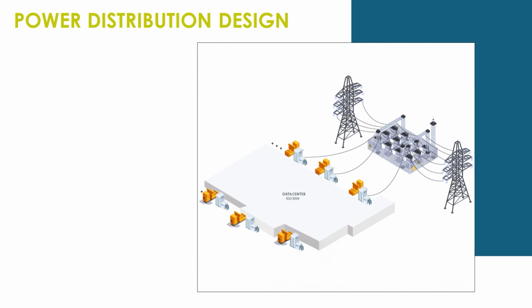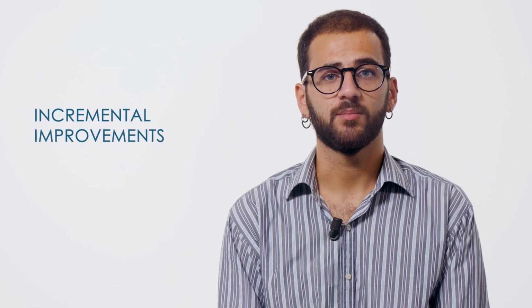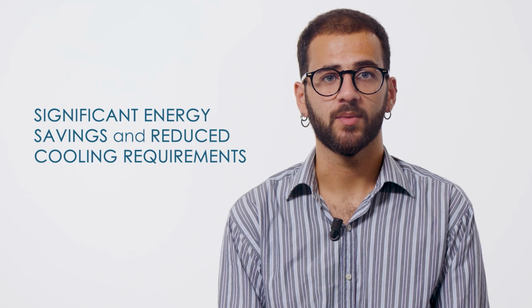Power distribution design is another critical area. Electricity losses occur at every stage of conversion and transmission. Traditional double conversion UPS systems operate at 92–96% efficiency, meaning several percentage points of energy are lost as heat. Similarly, minimizing cable lengths, using efficient transformers, and designing compact layouts all help cut transmission losses. Though this may seem like incremental improvements, at the larger scale of a data center, they translate into significant energy savings and reduced cooling requirements.